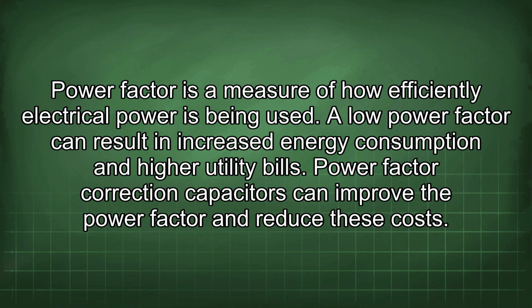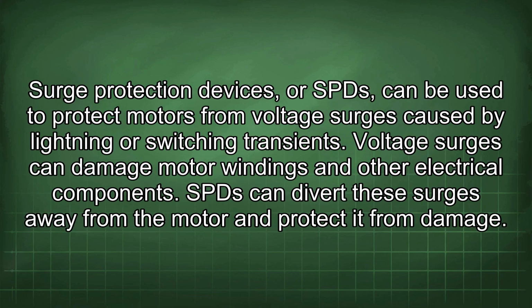Power factor correction capacitors can improve the power factor and reduce these costs. Surge protection devices, or SPDs, can be used to protect motors from voltage surges caused by lightning or switching transients. Voltage surges can damage motor windings and other electrical components. SPDs can divert these surges away from the motor and protect it from damage.